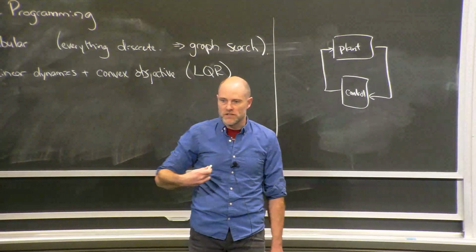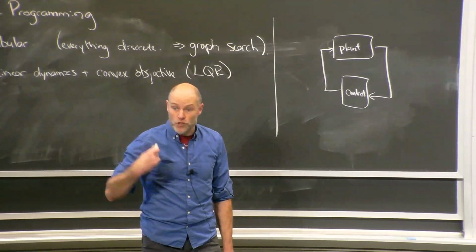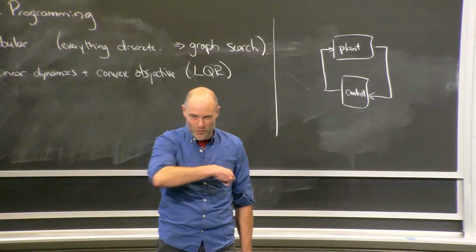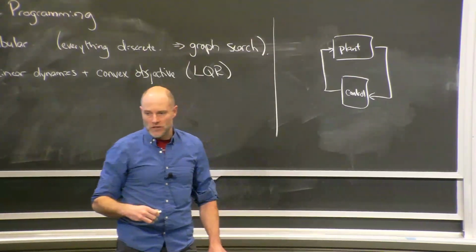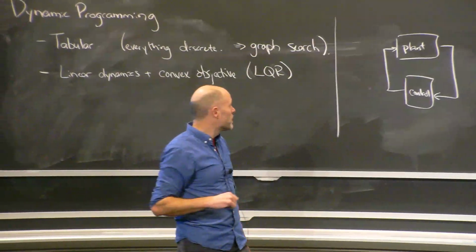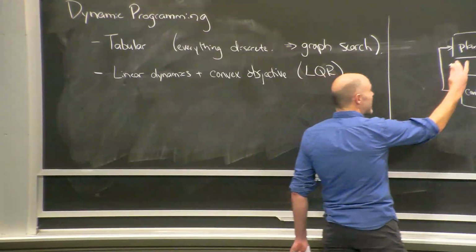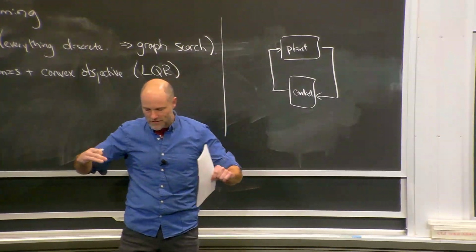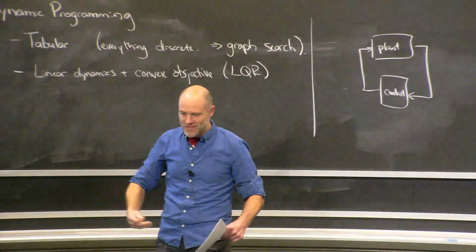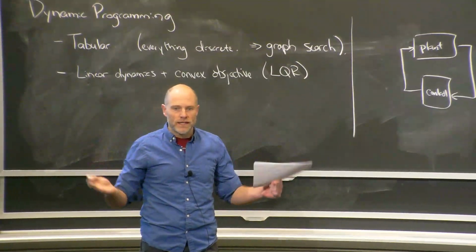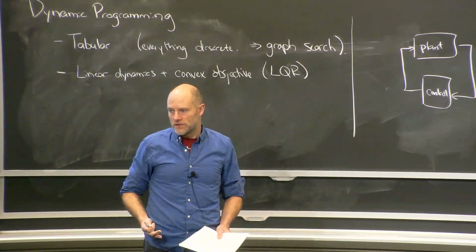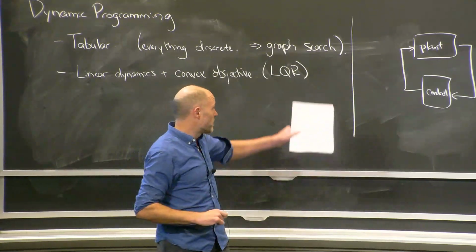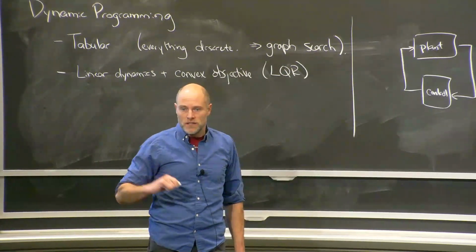Of course, there's the equations of motion, but there's also actuator models. There's sensor models. There's renderers that are one of your sensor models, right? There's a lot of things going on. And so, inside this environment model, you're going to find compositions of systems that are built into diagrams that can model much more complicated systems than you would be able to model with pencil and paper, or even if you just had to think about only a simulator that did physics.